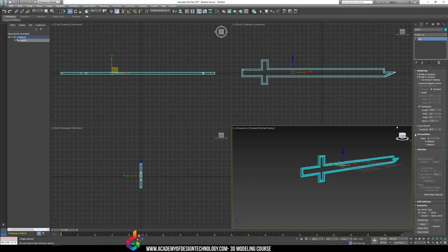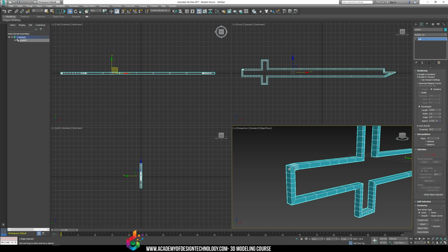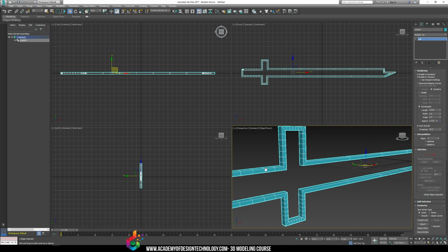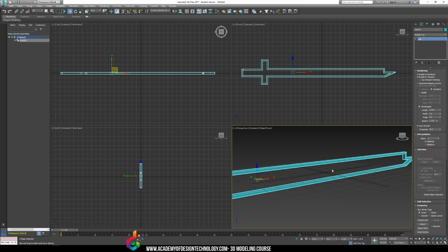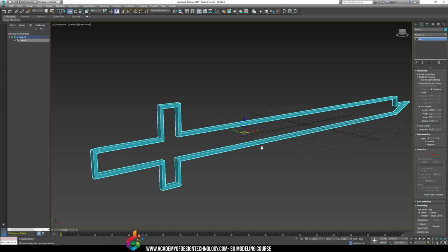And you can also change what's called the interpolation to make it smoother or less smooth by changing off optimize mode. And you can see now if I turn off optimize, we get a whole bunch of polygon counts here. Polygons created, and if I go to optimize, it actually reduces the amount of polygons in that model. I'm going to full screen this for a second.